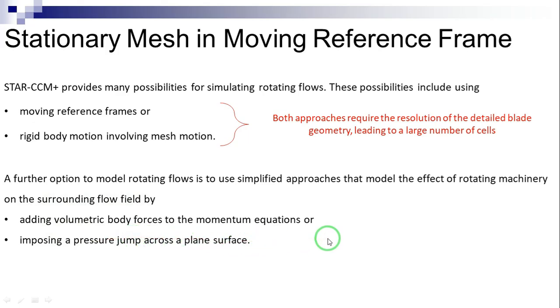These approaches are described in the following sections. In steady-state simulations or transient simulations that do not require precise time information, moving reference frames offer a method to represent rigid rotations or translations as a steady-state problem while keeping the mesh fixed. Moving reference frames can rotate rigidly or perform both rotation and translation in relation to the laboratory frame.